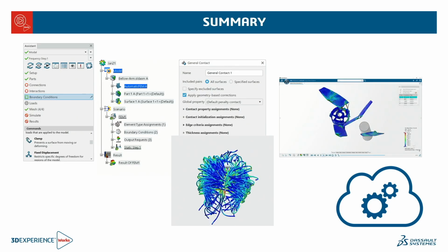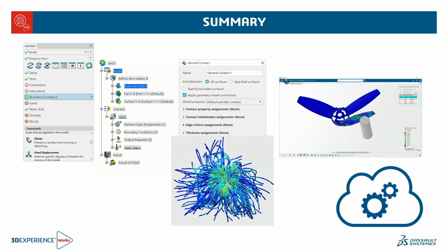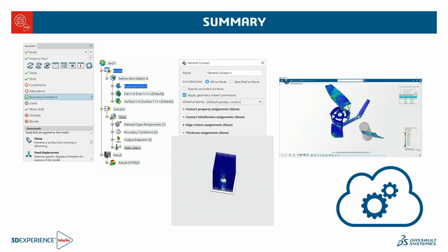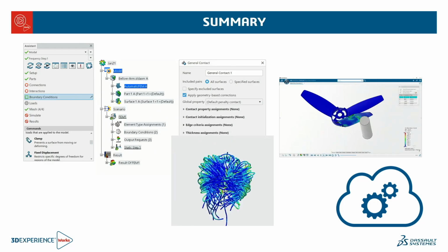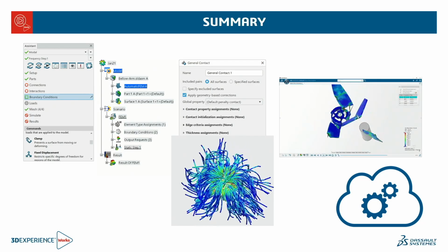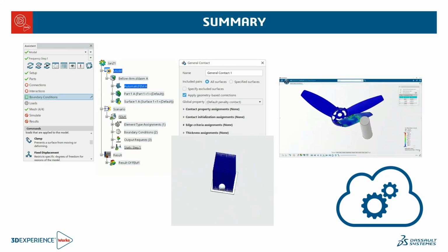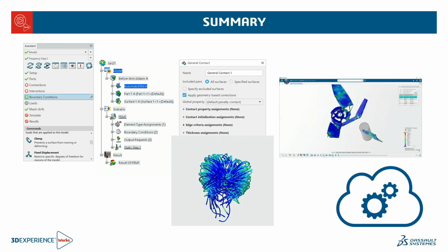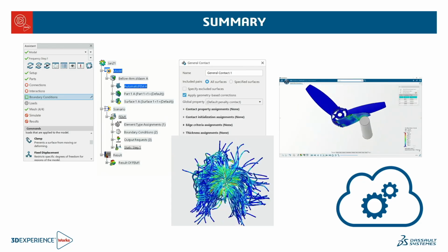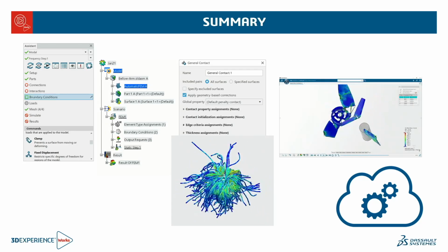But the number one recommendation, if you only remember one thing from here, and you're going into 3D experience, it is a very different interface to SOLIDWORKS Simulation. But the assistant keeps everything all together in one place and even gives you a kind of little traffic light guidance as to what you need to do to get through that. So you can set up most things here and then start delving into the more fidelity of the model, scenario, results.